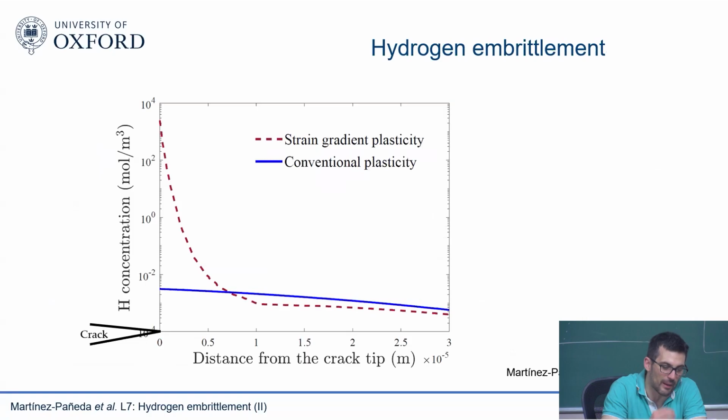And again, what you see is that the hydrogen embrittlement effect is twofold, because having higher stresses is not only relevant to achieve the stresses that you need, but it also increases your hydrogen concentration. So that's important, because then that degrades your atomic bonding strength as well. From an atomistic perspective, when you go to that graph and ask what my coverage of my interface is, your concentration is going to be very large near the surface. And this is what people have measured, basically.